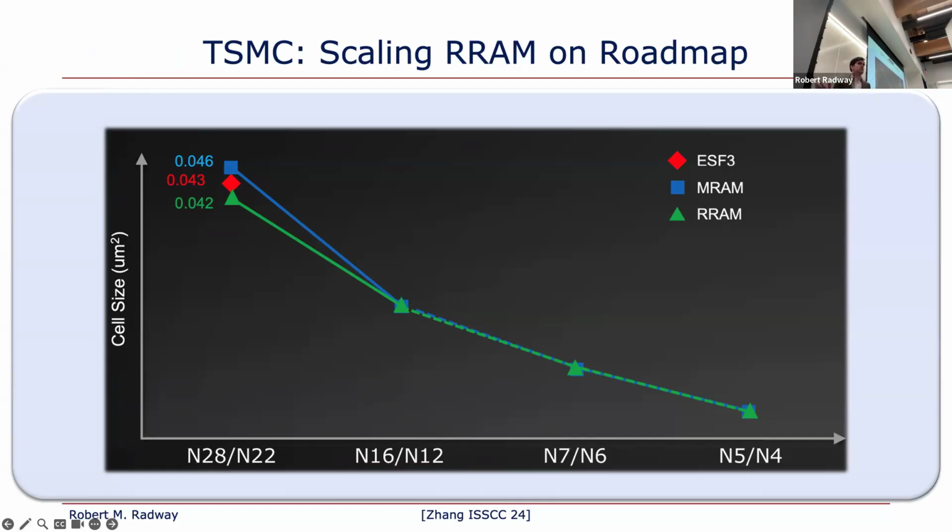But all of the Apples and NVIDIAs have specialized SRAMs, which are custom implementations of SRAM that are not the traditional 6T variant that we think of, be it for density or for retention. There are 7T and 8T variants that you can use. They're all looking at different memories, right? NVIDIA goes for HBM because it's a specialized DRAM that gives them performance. Apple has been looking at STT-MRAM, from what I know, which is another non-volatile memory with a different device function, but basically identical benefits to what we were talking about.